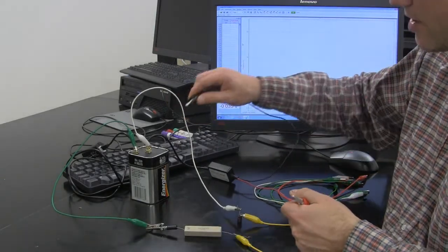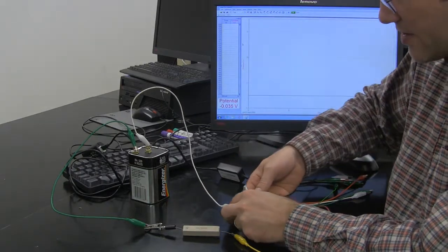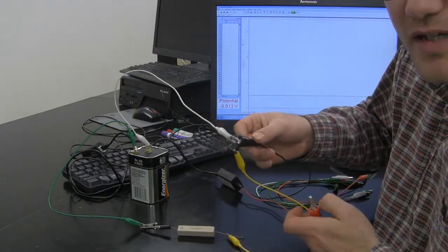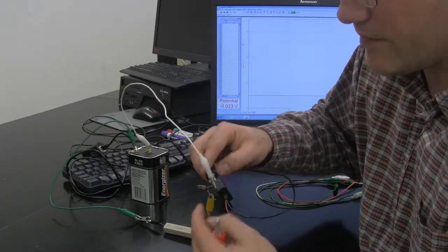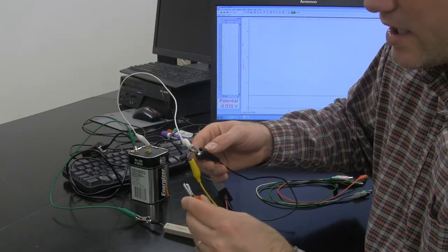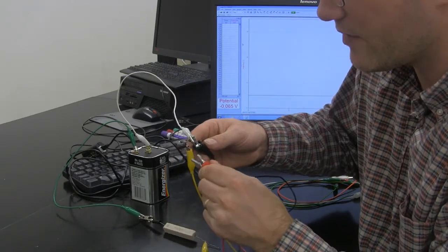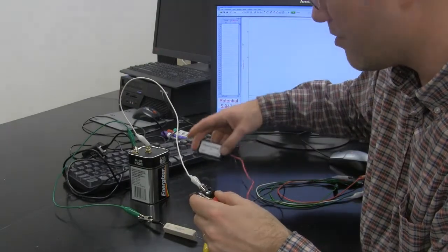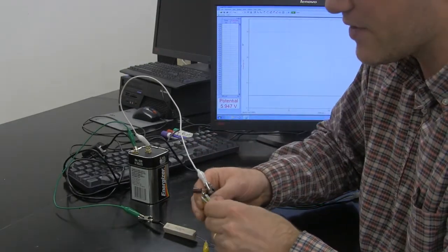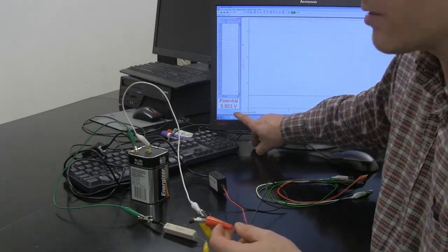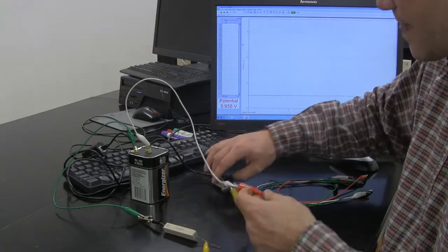This is the negative terminal of the battery, so let me trace it down here to the capacitor, and I'll clip it on to that alligator lead right there. And this is the negative side of the capacitor. Now the positive side here, I'll clip the positive terminal of the differential voltage probe over to there. And now if there's voltage on that capacitor, this is reading it. And you can see down here in the lower corner it's around 6 volts.